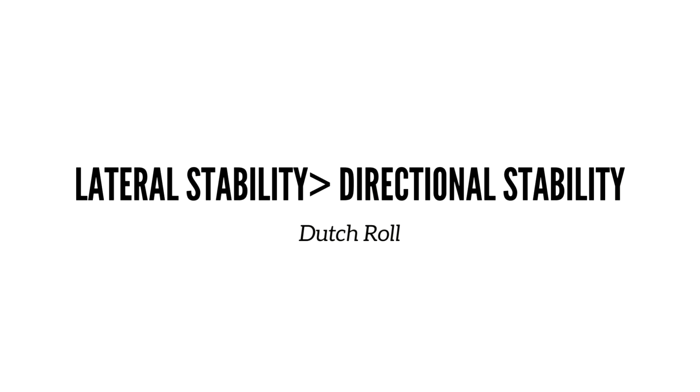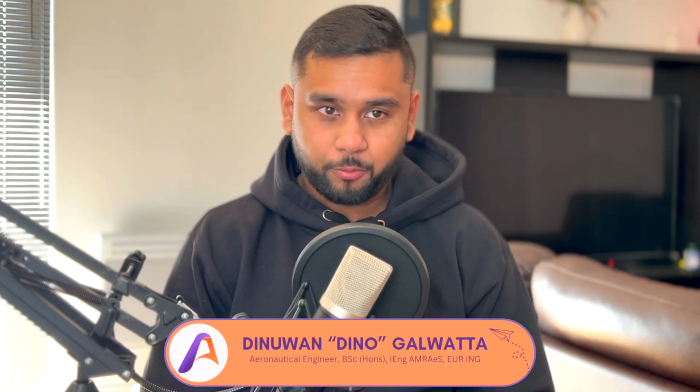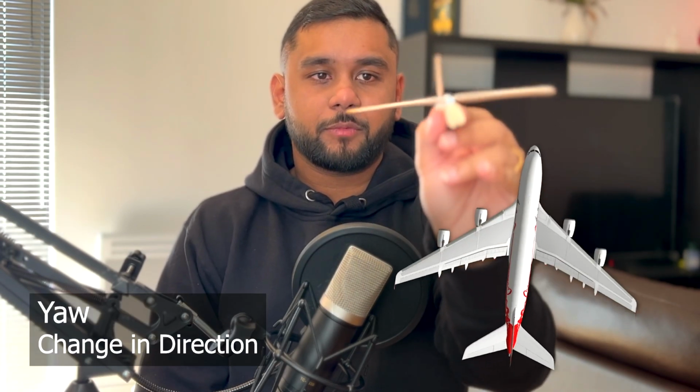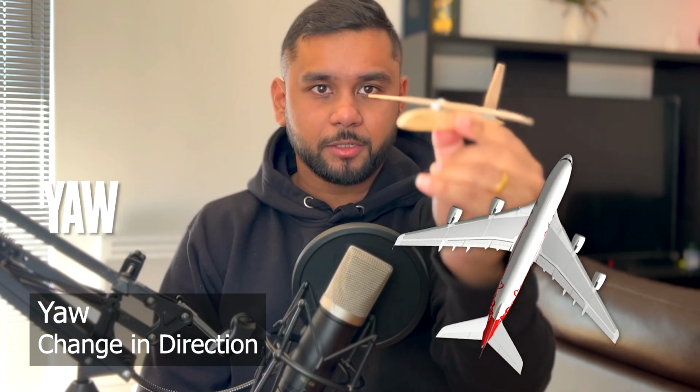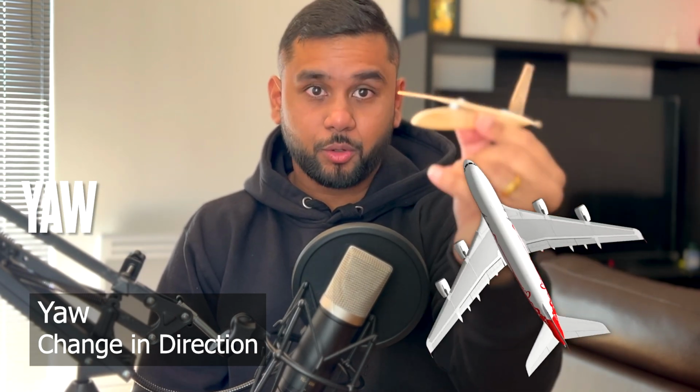So what is a Dutch roll? A Dutch roll occurs when the lateral stability is greater than the directional stability. What does this mean? Well, let me explain two terms going forth so it's easier to understand. So this movement, we call roll movement. Roll to the left or roll to the right. And this movement, we call yaw movement. That's yaw to the left, yaw to the right.